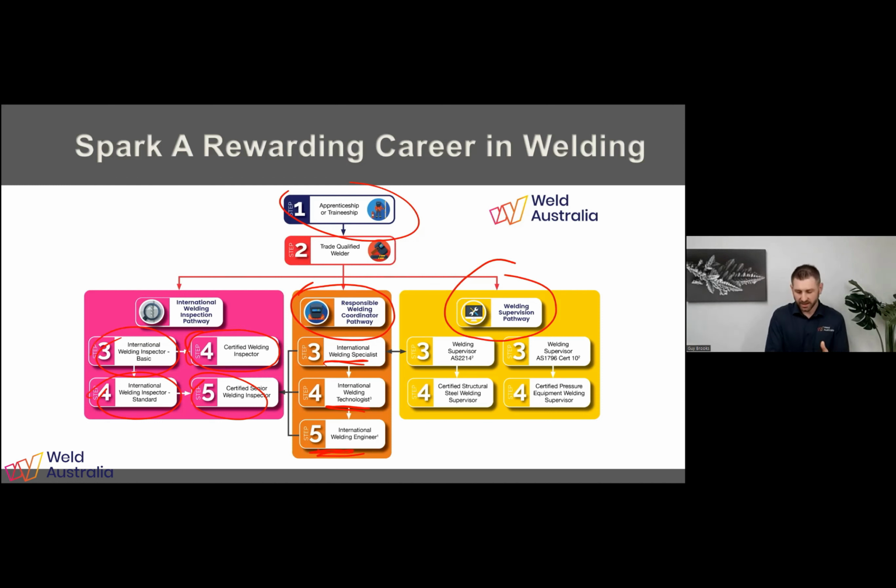Even though the inspector may supervise and watch the actual welder qualification test, your Cert 10 person is the one who looks at, okay, what is this material? Is this material a chromoly pipe? What about this material do I need to take into account? Does it need preheat? How do I know if it needs preheat? Do I get that from a manufacturer's data report? Do I get that from the material certs? Do I know what the material is? How do I figure that out?